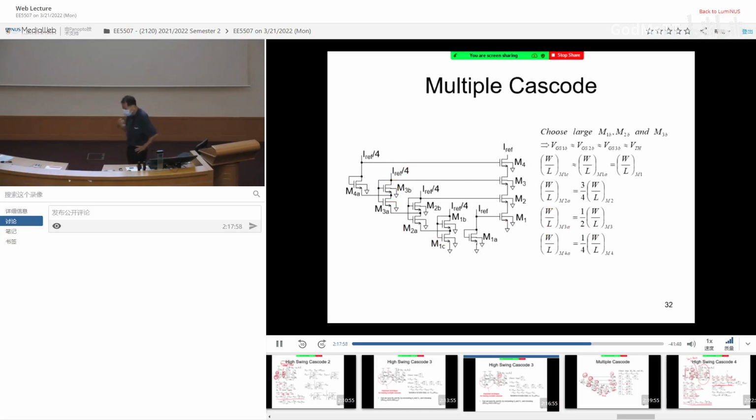And this technique becomes very useful if you have multiple cascodes. Just now, cascode method 1, cascode method 2, just a simple 2 cascode, the equation is already overwhelming, right? If you have 3 cascodes, it's even worse. But for this one, to get more cascodes is very straightforward, no need for calculation. You can see, the first transistor, we just use it to establish VGS, so that is very straightforward. Now the second transistor, this one, we use it to establish VDS set.